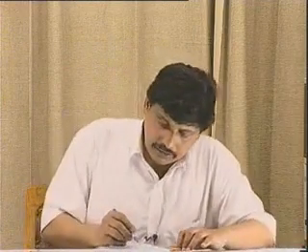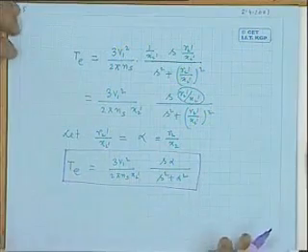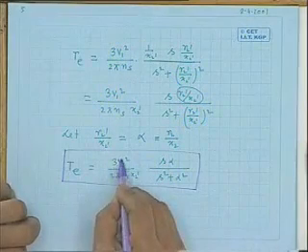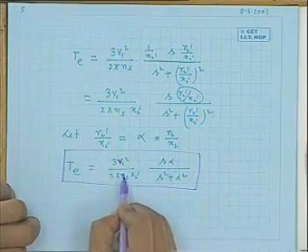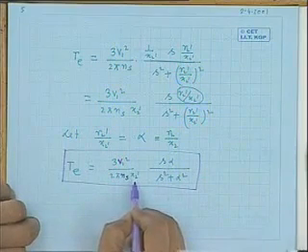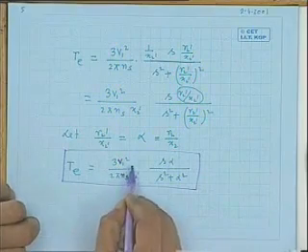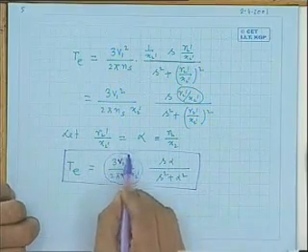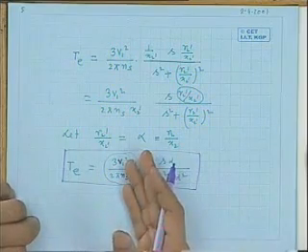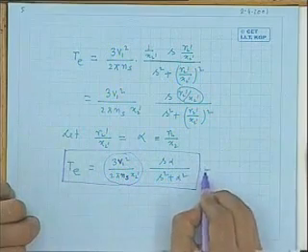Apart from that, we will see soon that alpha represents some important quantity in relation to the torque developed by the machine. So this expression is quite important. Also note that for the given machine, V1 is the rated voltage, Ns is the synchronous speed, and X2 dashed is the rotor leakage reactance per phase referred to stator. These are constants of the machine, if you are not changing them, and you will be applying rated voltage only.